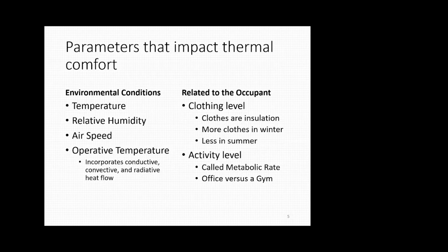And activity level is another thing that impacts thermal comfort. When you're in a gym and you're running around and exerting a lot of energy, you don't have as many clothes on. It doesn't need to be as warm in that space as it does, say, in an office, where you're sitting still and not exerting a lot of energy. You're going to be wearing more clothes in your office. So all of these things are related to thermal comfort. Make sure I didn't miss anything.